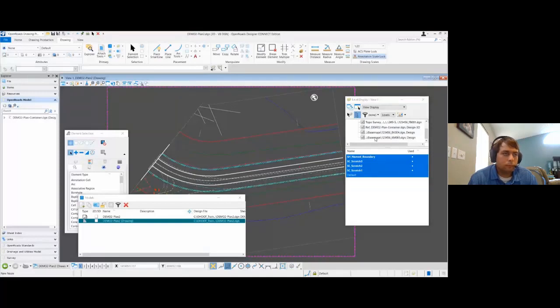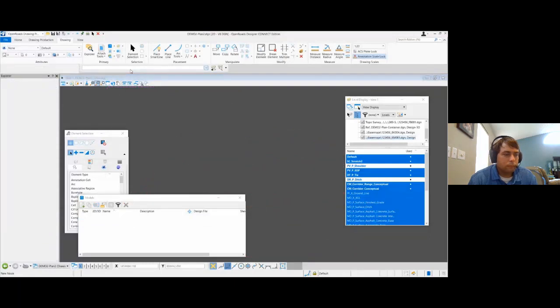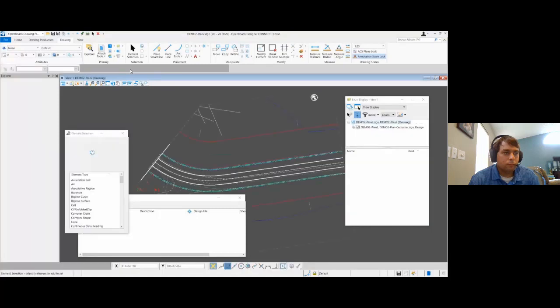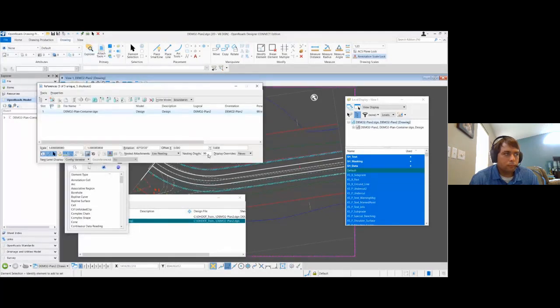So for example, if I wanted to turn off maybe the ditch, I turn it off, I save settings, and I reload the file, display override is going to say, you're not allowed to do that, and it's going to turn it back on. Okay, so I reload the file, you see it's back on, even though I saved settings.